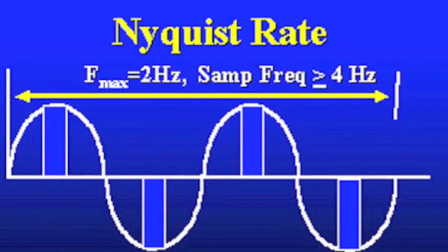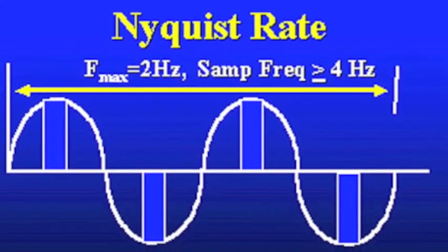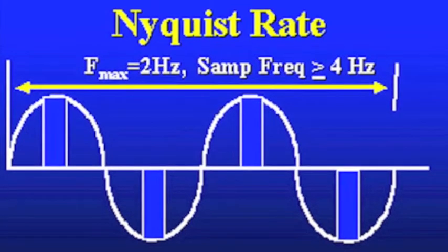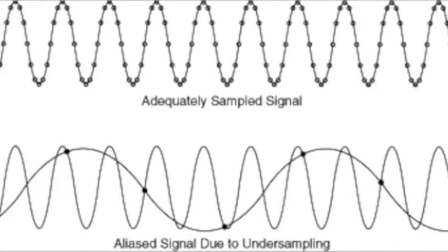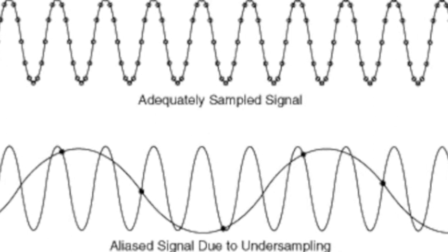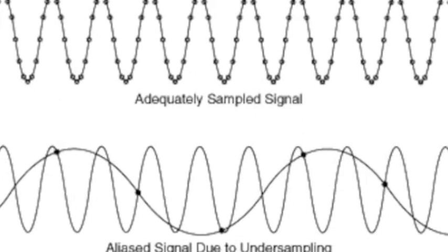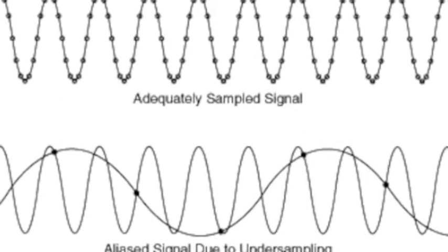Any information occurring above the Nyquist frequency might be confounded during data acquisition, and that is known as aliasing. In aliasing, signals become indistinguishable from each other and can seriously distort results. You can find more information on this in the resources section of your assignments document.